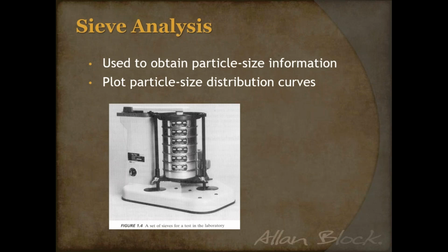So when we get into this, you have to start by classifying the soils, and a lot of it starts with the grain size. I know we've got some international attendees on this call, and I appreciate that. Every single classification might be a little bit different, but it all has to do with some type of particle size. This is a picture of a sieve analysis where they're shaking the different pans, and it starts with larger openings on top and goes all the way down to the pan on the bottom, which is 0. You just shake that over a period of time and collect how much of that original sample is collected on each one of those sizes, and then you simply graph it.